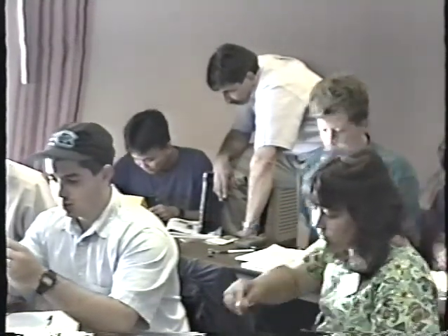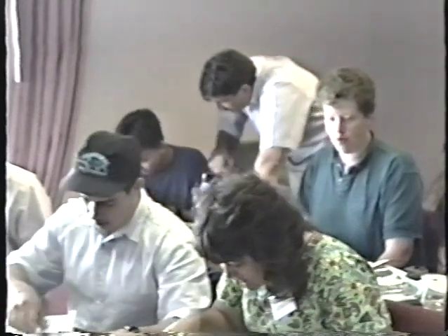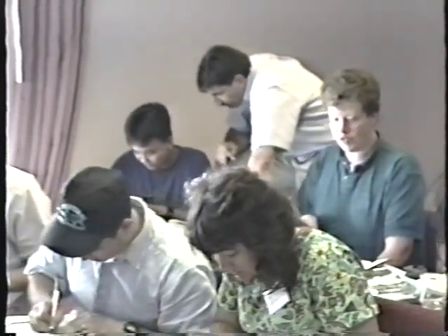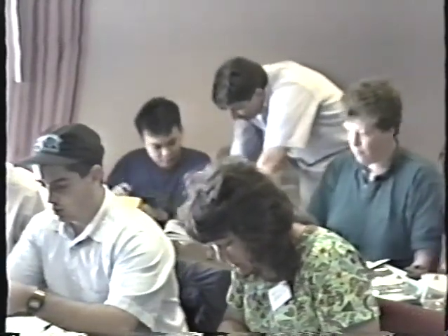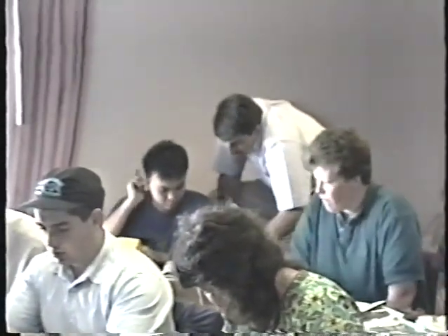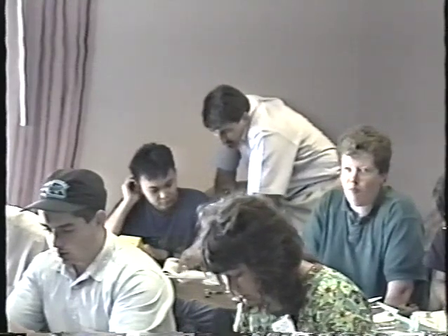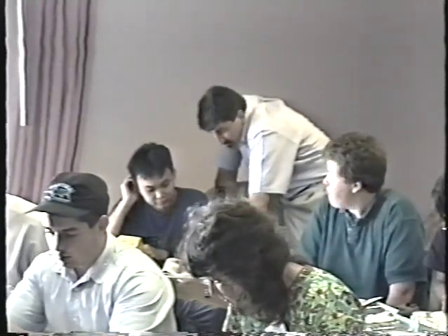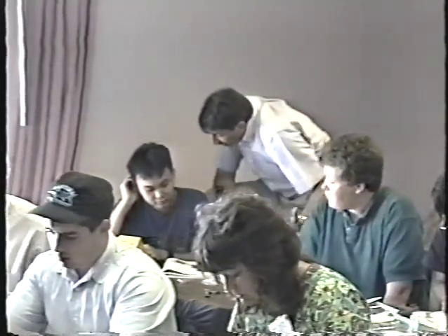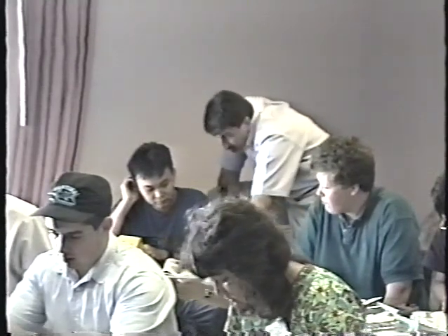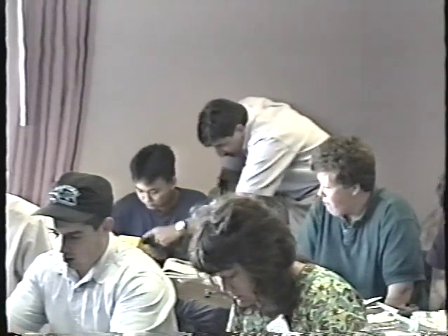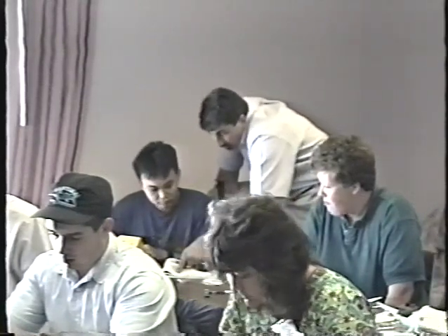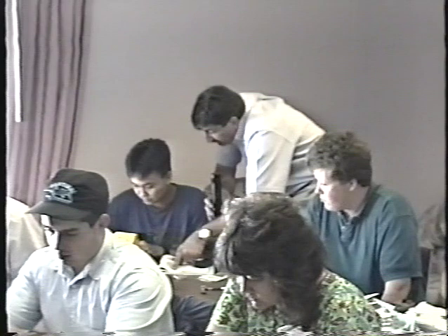That's the base there, isn't it? Base to emitter. Open. Now let's think about this for a second. Base to emitter. This time you got the open reading, correct? Right. Meaning so far it looks like a good PNP, like Dan was saying. It looks like a good PNP so far, doesn't it? Okay, let's keep going. Leave the red where it is. Move the black to the collector. OL. So far it looks like a good PNP.